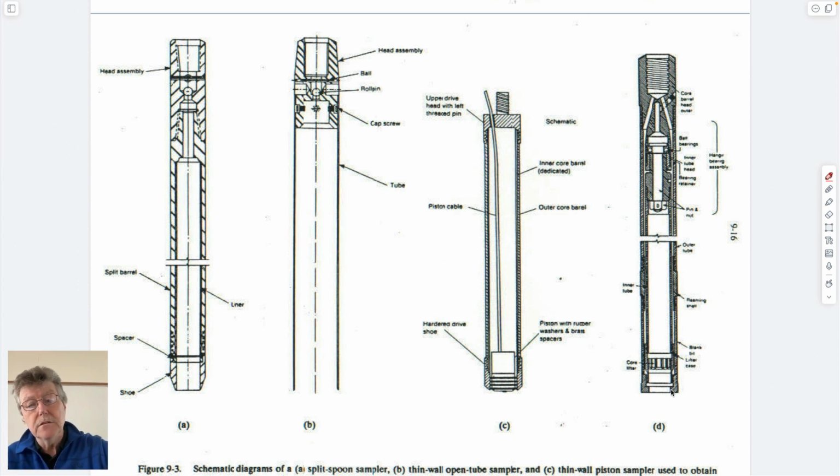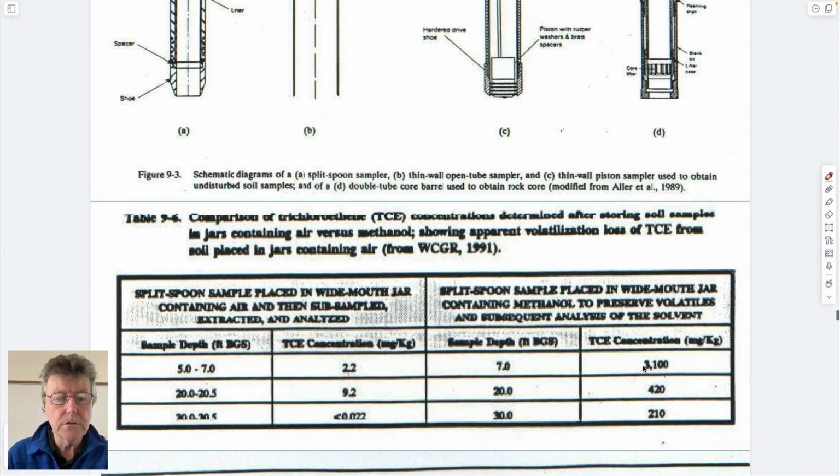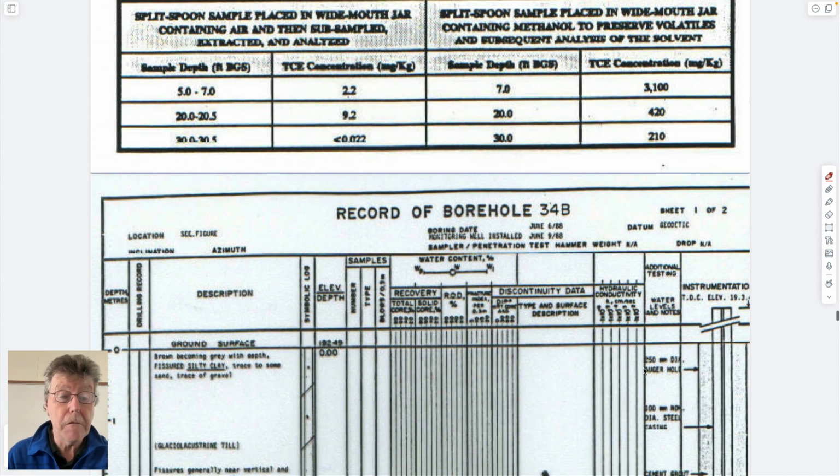We saw last time that there's an inner core barrel which is here. This assembly allows you to pull the whole thing up out of the hole without pulling all the drill stem to evacuate the hole, which takes a long time if you're down a couple of 100 feet. And this has diamonds studded at the tip, a core catcher at the bottom, which is like a comb, which is spring steel, which stops the core from dropping out and rather takes it up to the surface. And so those are the kind of things we're talking about.